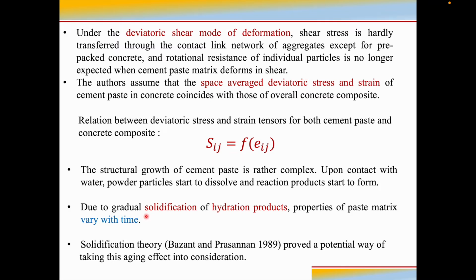Due to gradual solidification of hydration products, properties of paste matrix vary with time. So here is very important: the process of hydration is strictly related with time. Solidification theory provides a potential way of taking this aging effect into consideration.